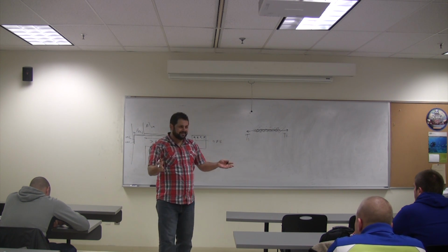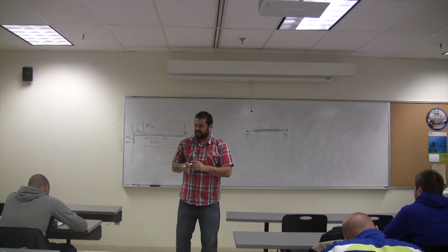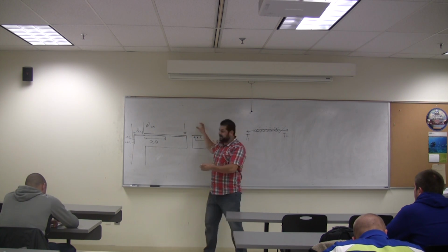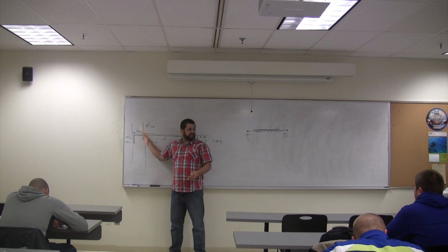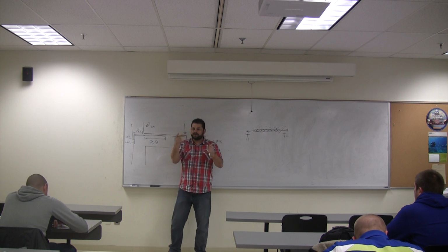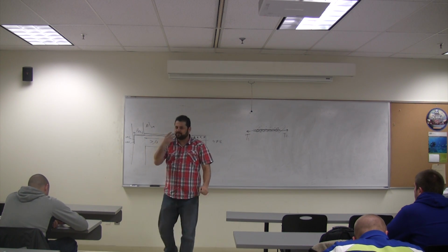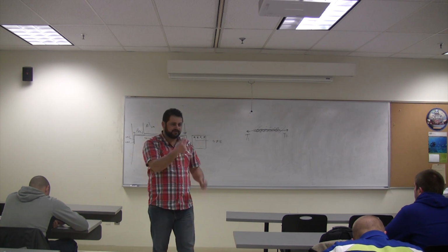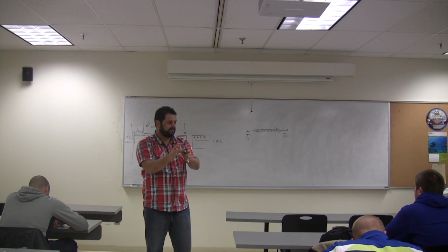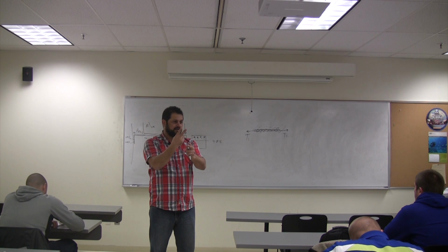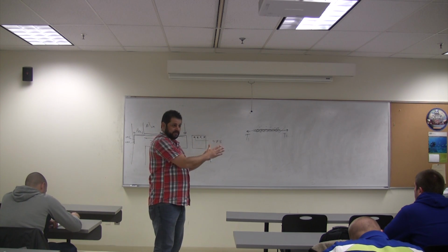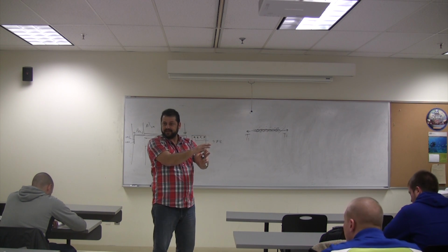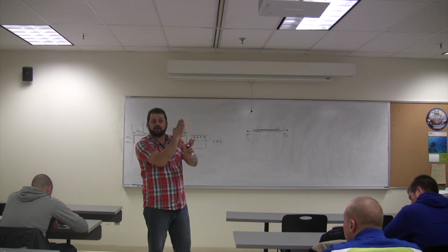From the moment diagram. Because look, why do we use 4 bars? So that we have the design moment here greater than the ultimate moment here, right? Now, what do you do? You calculate the strength of your section for 2 bars. You can calculate the design moment for 2 bars only. You go to your moment diagram. You find the location where the moment becomes that value. That's the theoretical cut-off point.